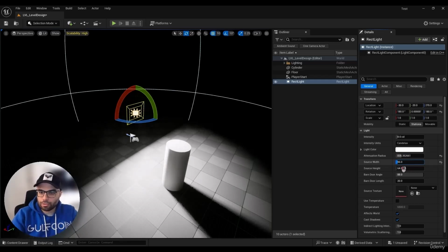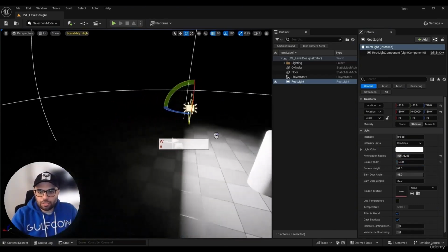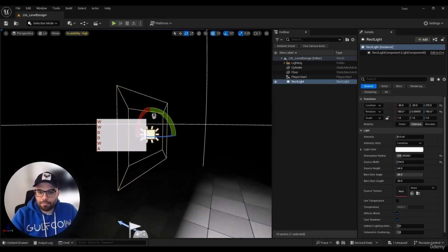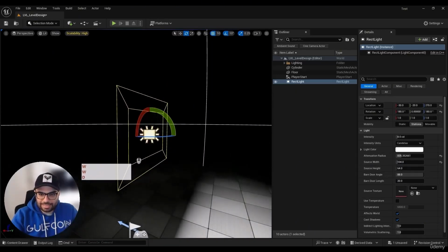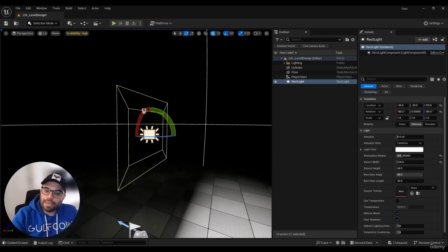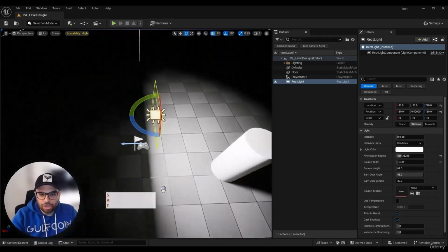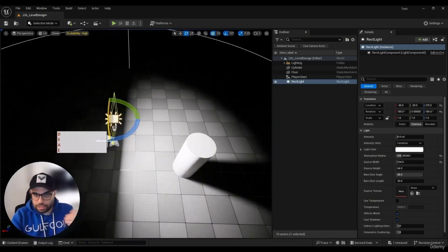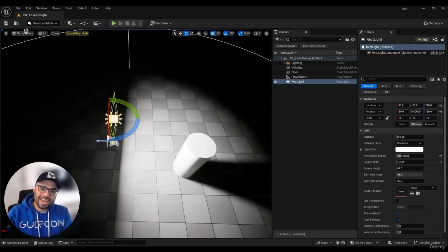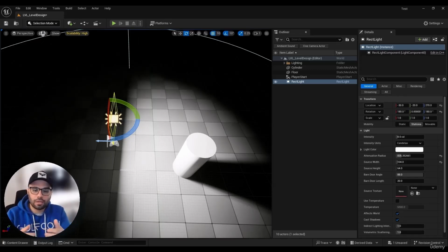Barn door angle is what you see on this edge. This middle rectangle of ours becomes our light source, and this barn door, these components that exist, become the direction of the light. Now look, the direction of your light is like this. You have a light plane, and it is practically doing its lighting 180 degrees. Many times we don't need something like this, and we want to limit it. We don't want this light surface of ours to diffuse light from all angles. This is where we use this angle. If we set it to 90, well, it becomes perfectly straight. If we reduce it, you see the diffusion angle of the light is becoming more limited.